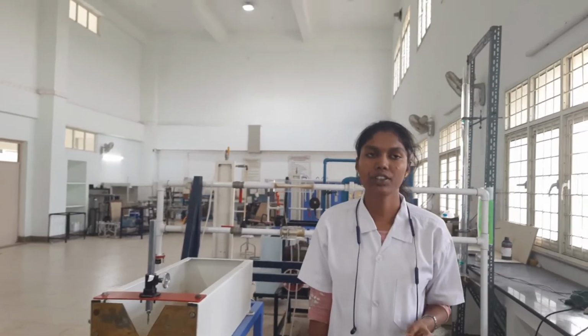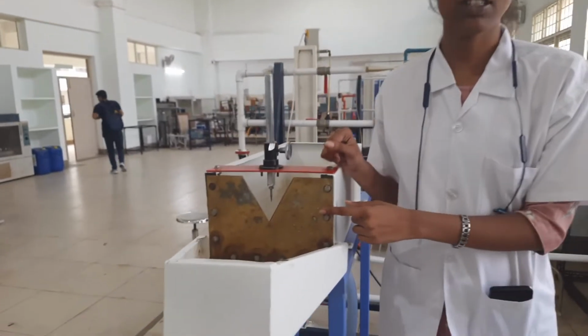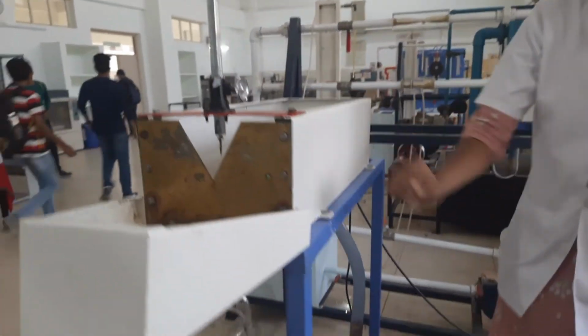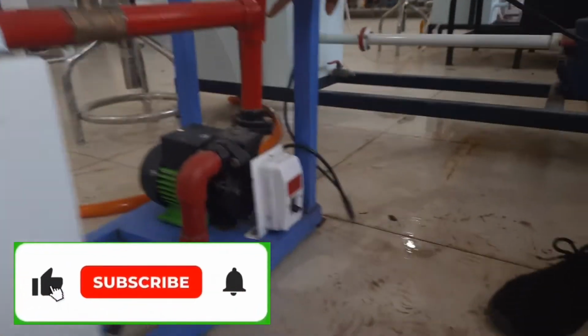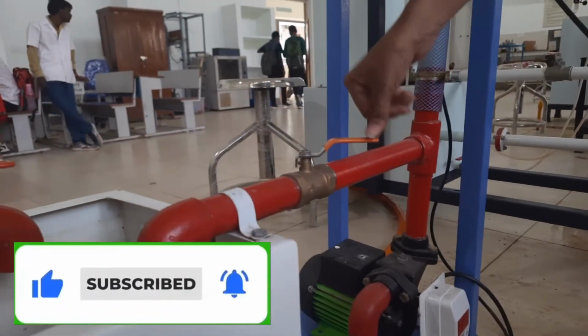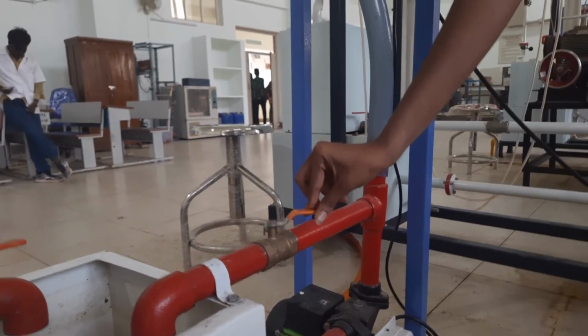The procedure for flow through notches. Here in this experiment, we'll have a V notch, which we have to connect to the notch tank, and then we need to switch on the pump by switching on this motor. Then we need to vary this valve so that we can change the volumetric flow rate.